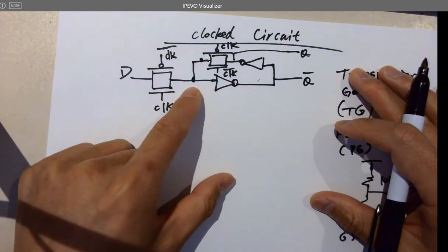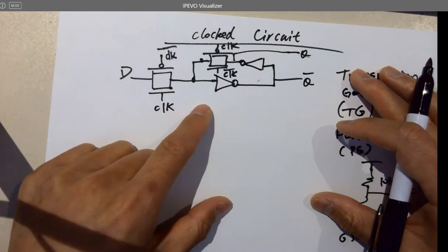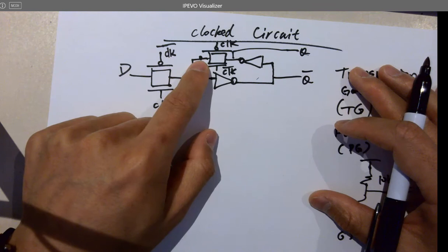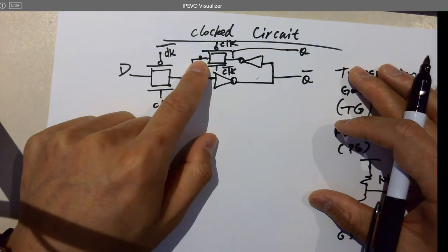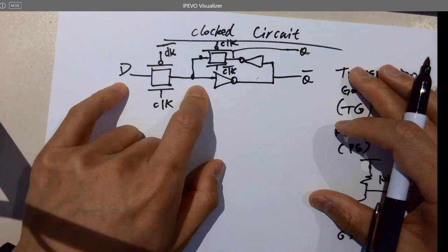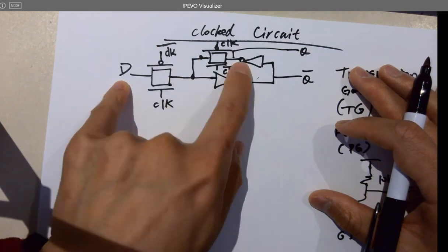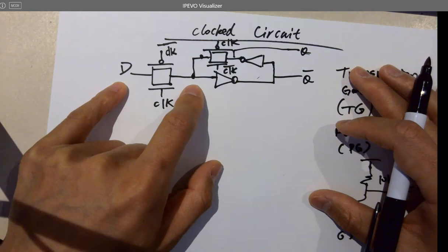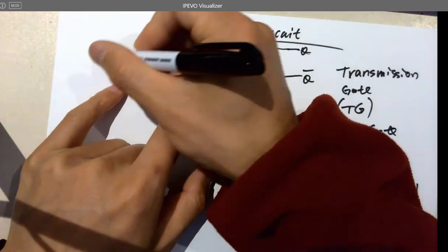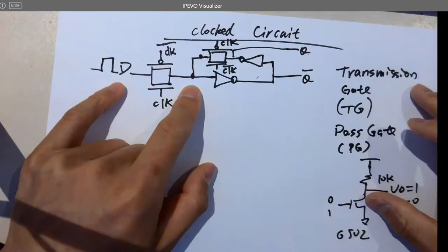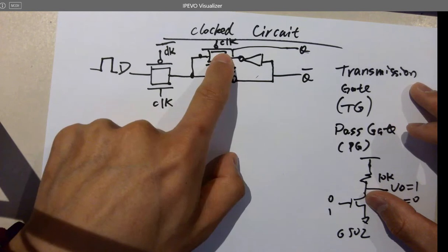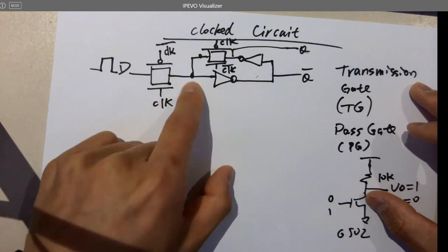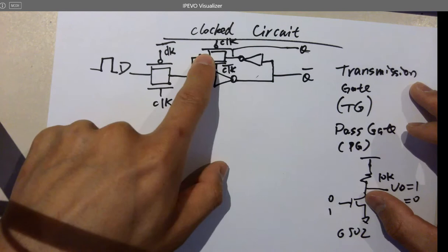Why? It's just still that wire, right? It's not like on or off, but it's going to be something like 2.5 or so. So why is it different, keeping it on or off? You're passing either ones or zeros from the data point, right? So the data is being sent to here and to here. So whenever data is being sent to here, you want this one to be off, so it's not conflicting with the input here. Why, when it's off, is it not conflicting?